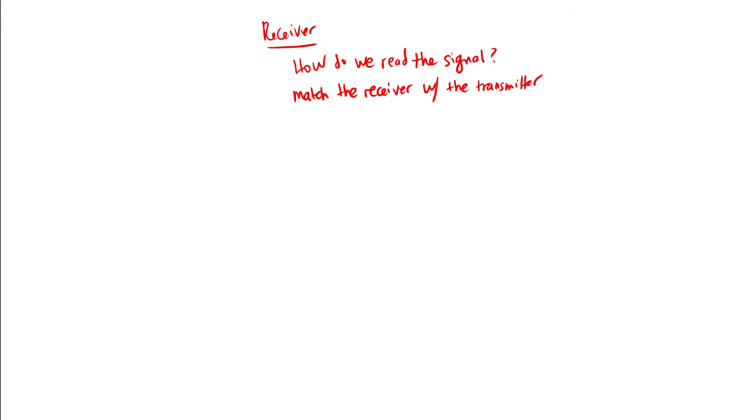So, sensitivity. If I have a 56 gigahertz laser, then I need a 56 gigahertz receiver. If I buy a cheap receiver intended for an LED that's 600 megahertz, I won't be able to pick up my signal from a high powered laser.